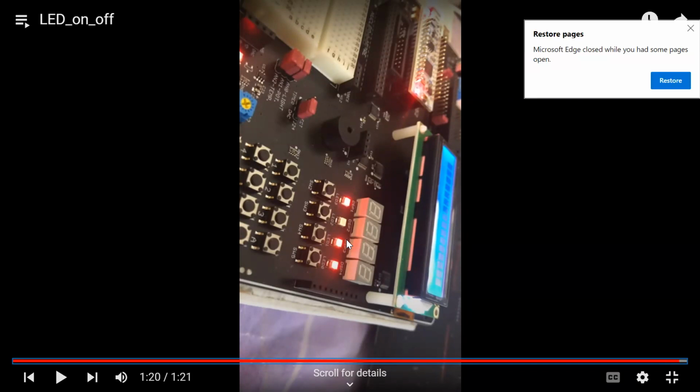We use the same idea in interrupts. In interrupts, we can do multitasking, as I'm going to explain later, okay? So your program is not going to be written in one place anymore. I have one task in the main, one task in one interrupt subroutine, one task in another interrupt subroutine. And then I can run multiple tasks at the same time. How? Similar to this idea. In reality, I'm going to run only one task at a time. But if I can do it very quickly, you will feel like all of them are working at the same time, which is not true. You got what I'm saying?